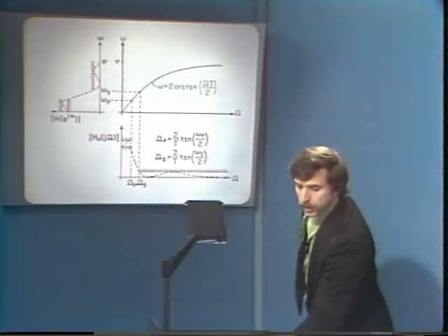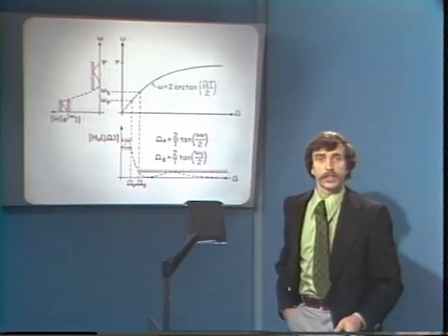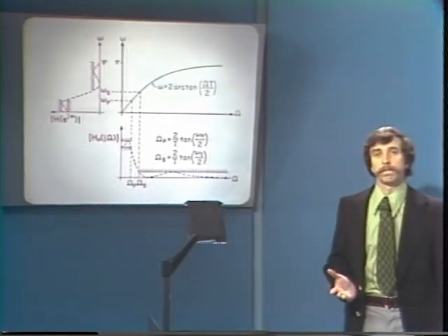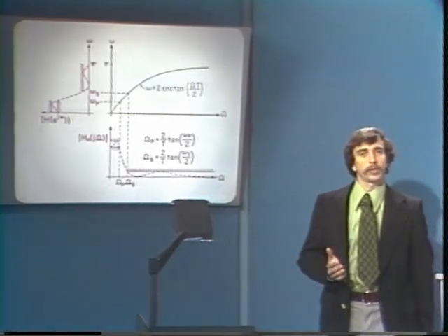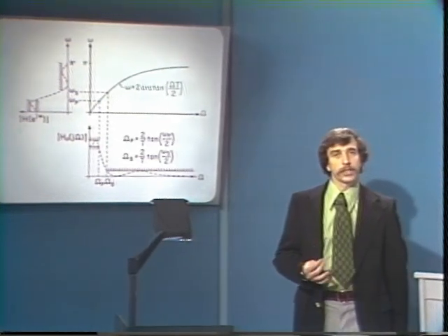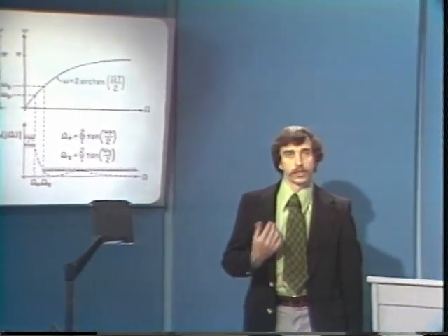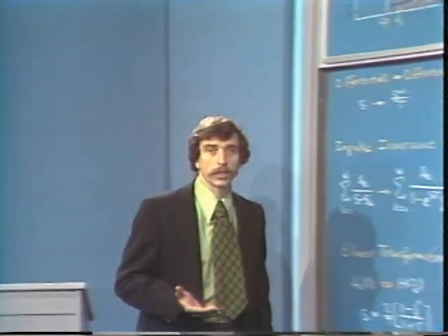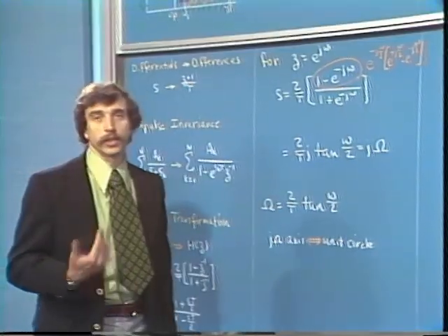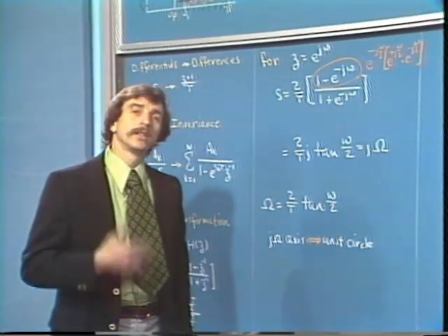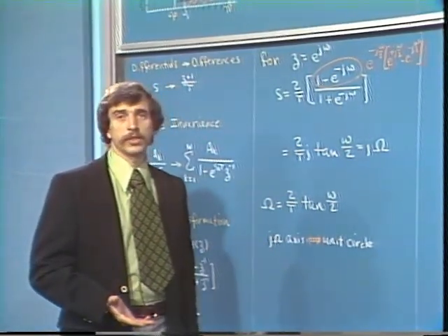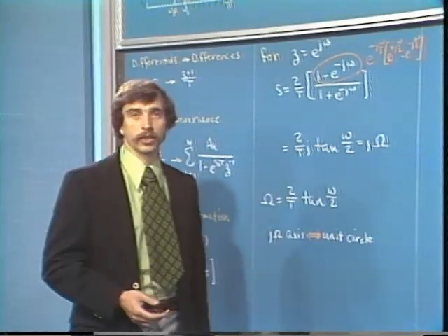So the key point then about the bilinear transformation is that it avoids the problem of aliasing at a price. The price is that there's a distortion in the frequency axis, and so consequently we can only use the bilinear transformation to design filters that can tolerate that distortion. Typically, that means designing piecewise constant digital filters.